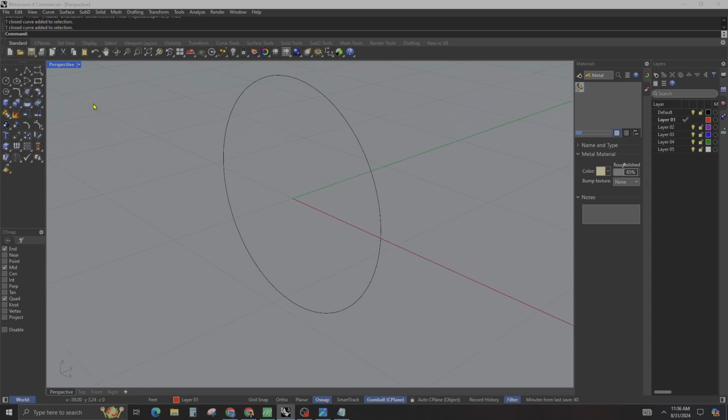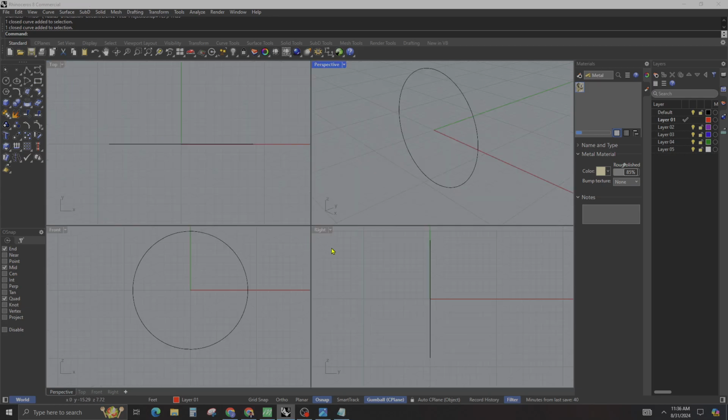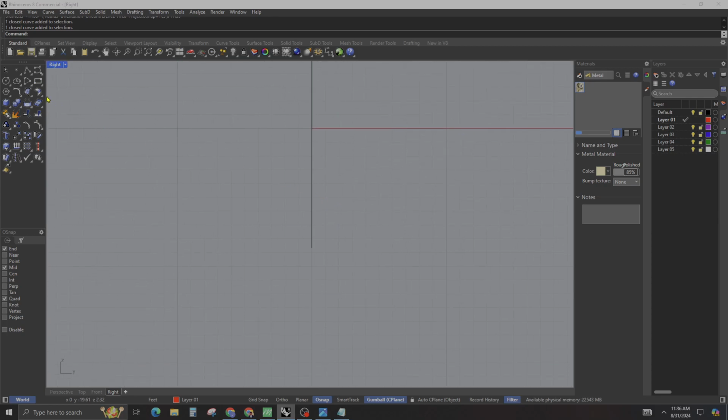All right. So now let's go to right view over here. Let's draw another circle, and then let's choose this circle 2 points right here. So over here, click this, left click to your quad, and then you see it's red. And then now we can type our circle to 1.6 diameter, and then shift.